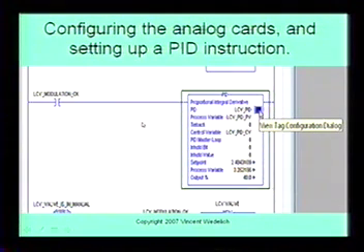Okay, so here's an actual example. And you've got level control valve modulation OK. So whenever this bit turns on, you're going to allow this thing to control, right? And so you've got PID, level control valve PID. It's a tag, right? It's a real value. Process variable, level control valve underscore PID underscore PV, process variable. And these can be any names you want as long as they stay within the tag convention.